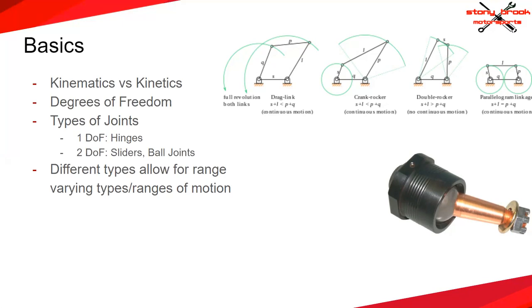So, bringing this over to some examples of types of joints. If you have a hinge, that's a single degree of freedom joint because it can only rotate. So in theory, you only need to define its location with a single angle. Whereas if you have something like a slider on a plane, it can go in 2 dimensions. Or if you have a slider on a hinge, that's technically a 2 degree of freedom system. The slider moves only along a line, so you need a variable to define where it is along the line. Likewise, you need a variable to define the hinge.